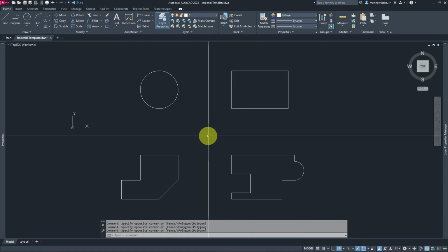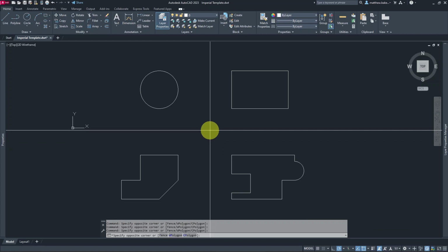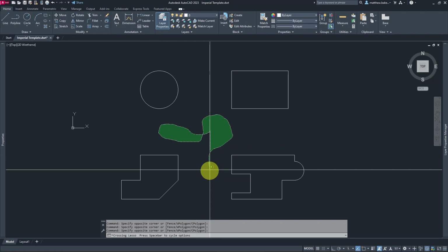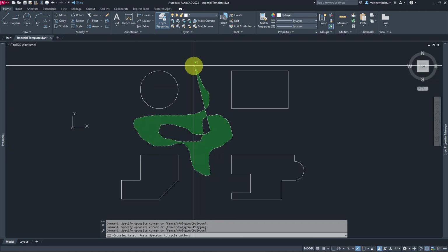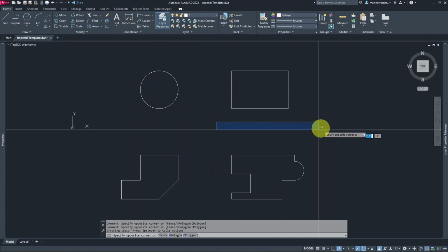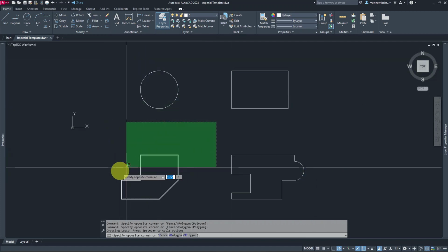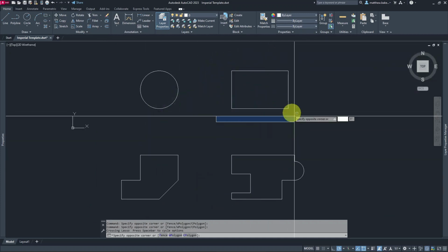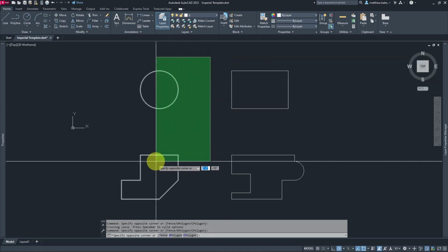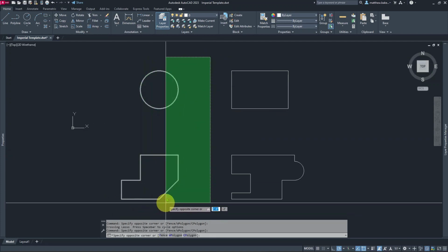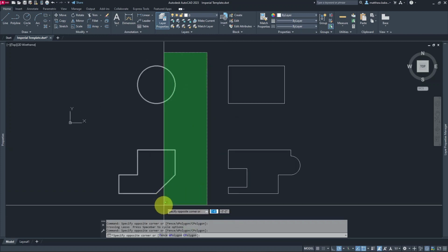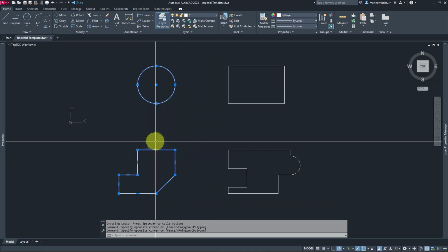And also, I don't personally use it a lot, but if you press and hold the left mouse, you get what's called the lasso. So these are all different ways to select objects within your drawing if you're in a tight space. But to me, just the rectangular one click and then lift your finger to drag the box does the trick. So the difference between the two: green is every object green comes in contact with, even if it's not the entire object, it will select it.